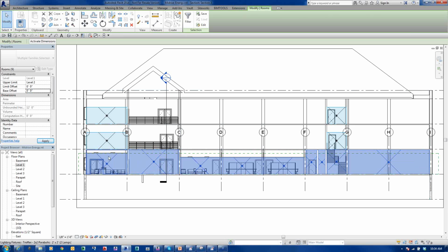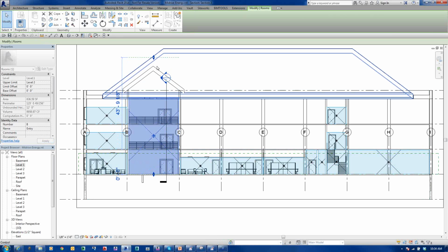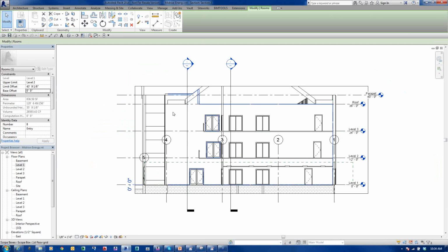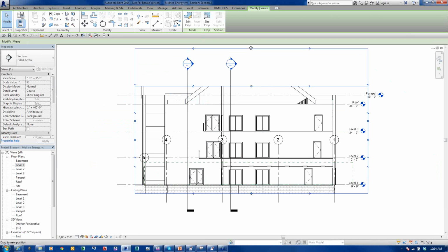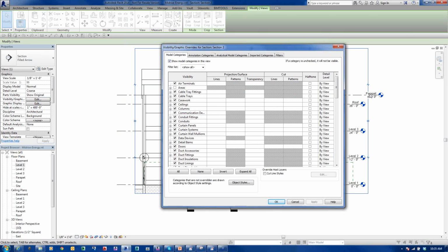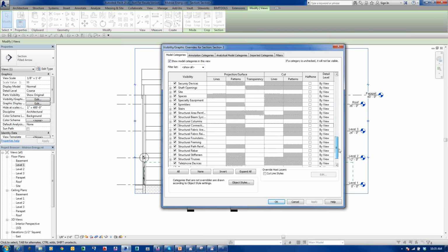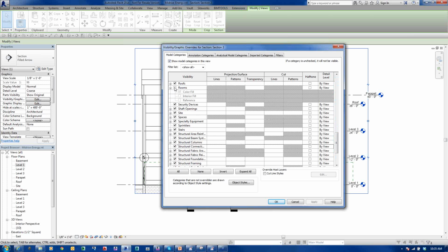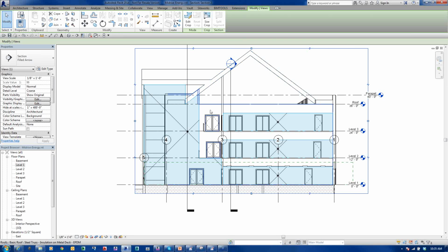Okay. That'll correct all these room volumes in here, and you'll see they'll snap up, except for this lobby area. I'm going to have to come into this one and stretch that all the way up so it's properly enclosing that room volume. And we can see this in this section over here. So I'll turn on my rooms and areas in here just to show you some interesting things that are happening with your room volumes as we're doing this process. So I've got the rooms in here, turn those on, turn on my interior fill. We can see this is what's going on.